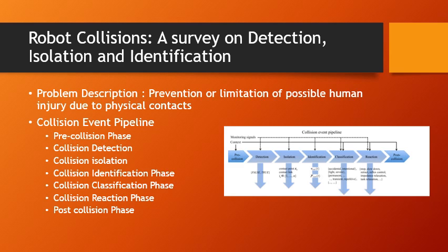An intuitive approach is measuring the electrical drives, looking for fast transients possibly caused by a collision. A mechanical limitation based on the model control law is inherited by the controller, but it is not possible to reliably detect collisions in a highly varying dynamic environment.